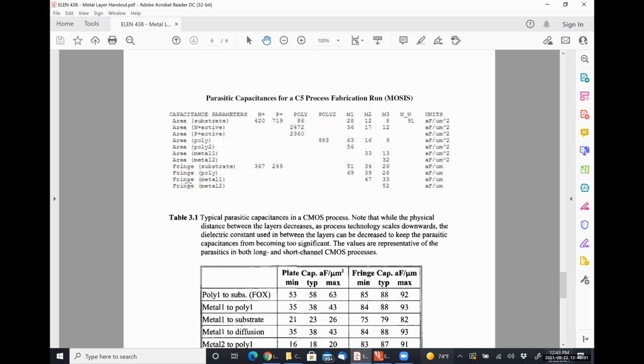And so you could neglect your fringe capacitances. Well, here we can make capacitors that are parallel plates where they're not even remotely close to infinitely long planes, right? They're orders of microns in length. And so the fringe fields start to play a very significant effect.